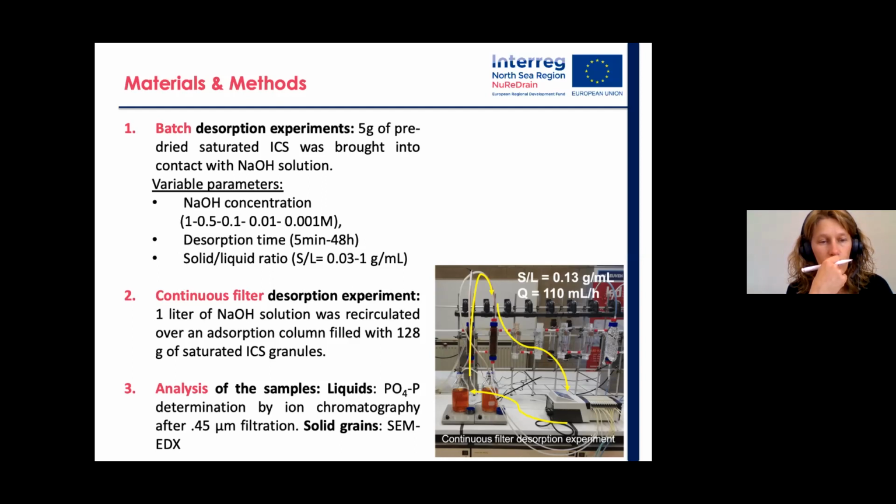So afterwards, we did all the analysis on ion chromatograph and ICP, but the solids were analyzed by an electron microscope with the option to see where the phosphorus is in the granule itself, and it's done by EDX.